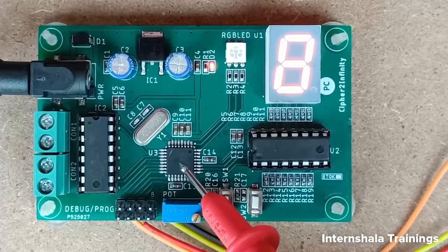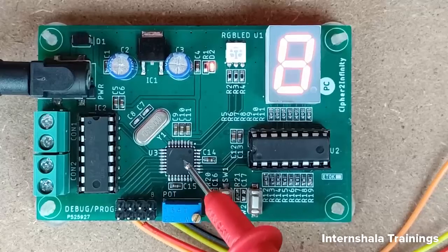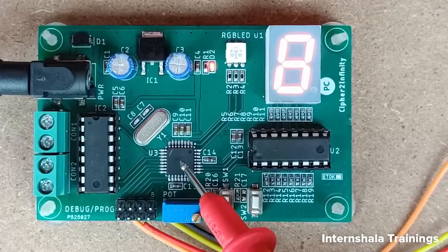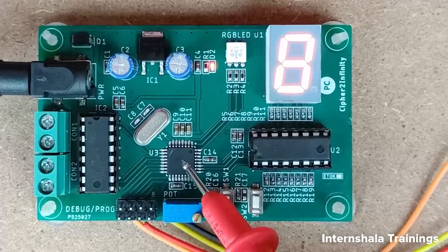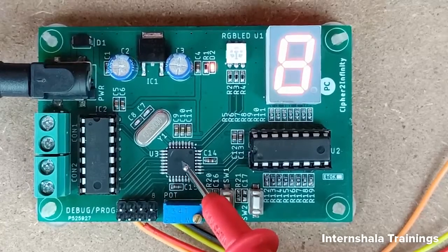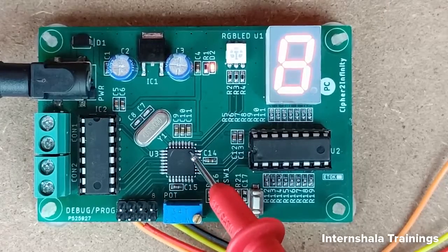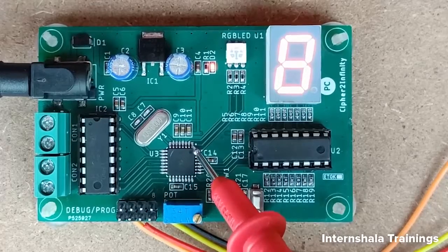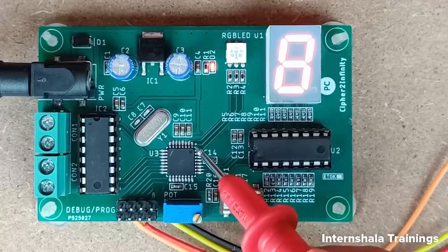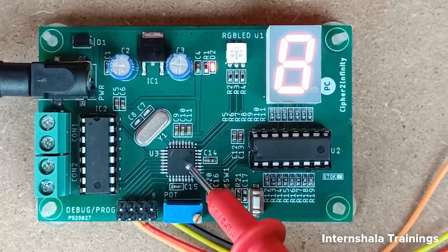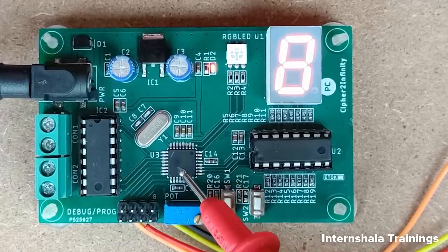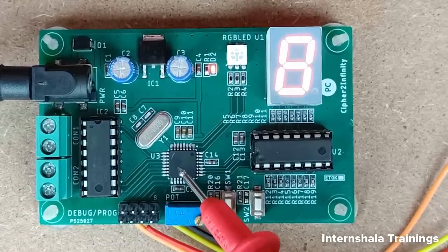So when you solder the IC on the PCB, you have to make sure that you are soldering the IC in the right orientation. I have actually made this particular mistake multiple times when I was getting started. So that's why I'm emphasizing that you have to solder the IC in the right orientation. You know that the first pin, which is on the left-hand side of the notch, is pin number 1, and you have to match pin number 1 of the IC to pad number 1 on the PCB. So always remember, you have to solder the IC in the right orientation.